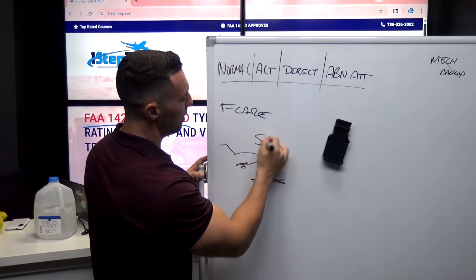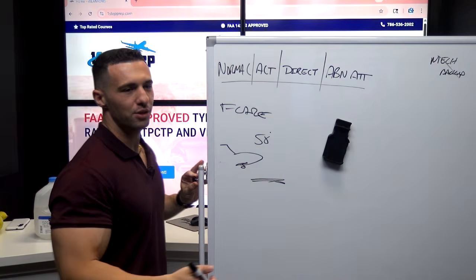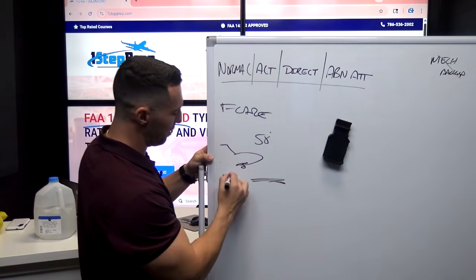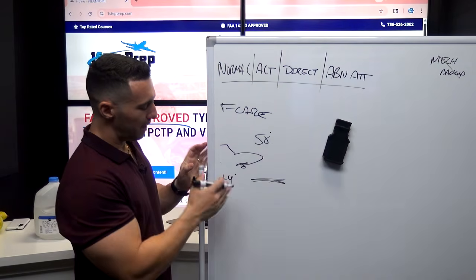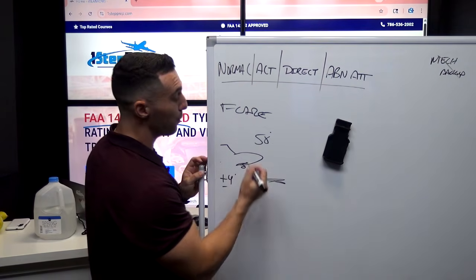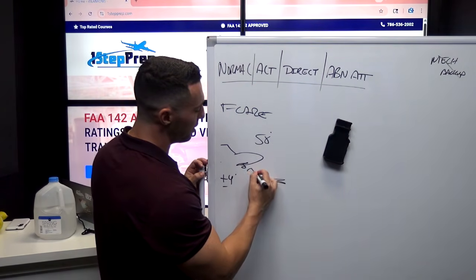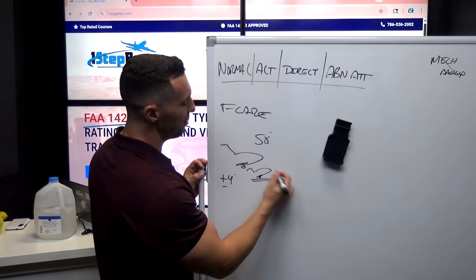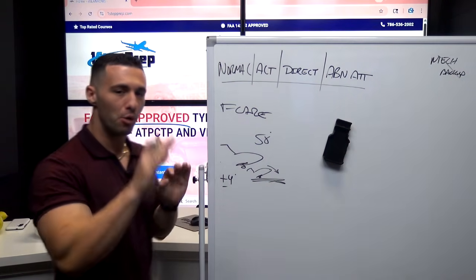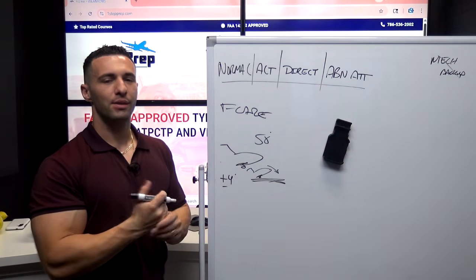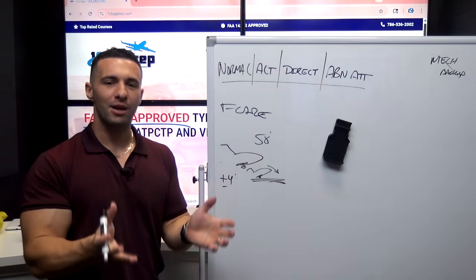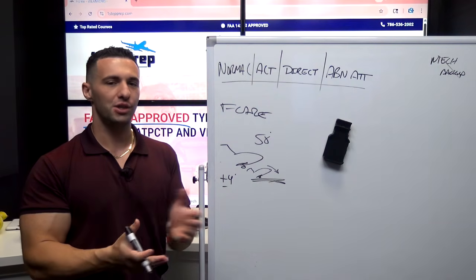at 50 feet. And as an example, I'm going to say your pitch attitude here is, say, a positive 4 degrees nose up. So plus 4 degrees nose up. It takes that picture right there, and then at 30 feet, it begins applying a nose down pitching moment that you're going to counter with aft elevator input to make the landing flare seem natural and normal by comparison to any other jet you've landed.